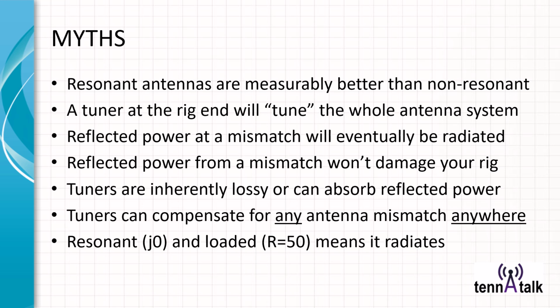A tuner at the rig end will tune the whole antenna system. Well, it depends on what you mean by tune. I wouldn't call it tune, I would say accommodate is more likely. A tuner accommodates it and keeps your rig happy, but it doesn't help the movement of your power out to the air on the antenna end. Reflected power at a mismatch will eventually be radiated. Not really.